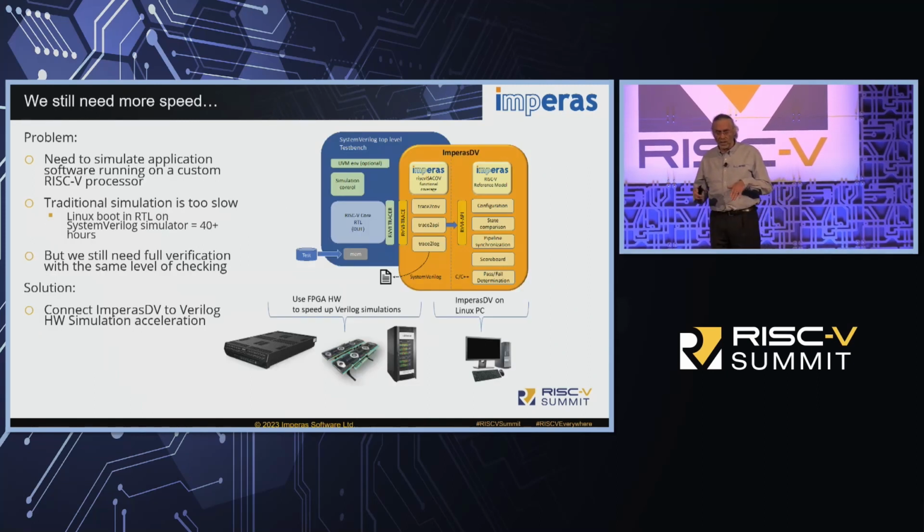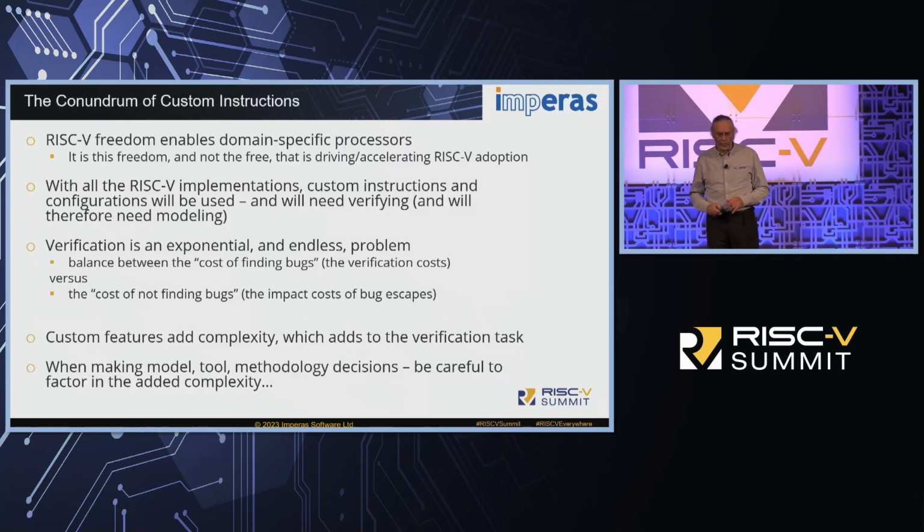But the challenge is, it still takes a long time. Booting Linux on that CVW core takes 40 hours on a Verilog simulator. So we started working with the big EDA companies with their hardware assist to try and improve this verification, because we think we can probably get what was 40 hours down to about 5 minutes. So that means if you find bugs, you can turn around much more quickly. So we're working on that, and that's something for the future there.